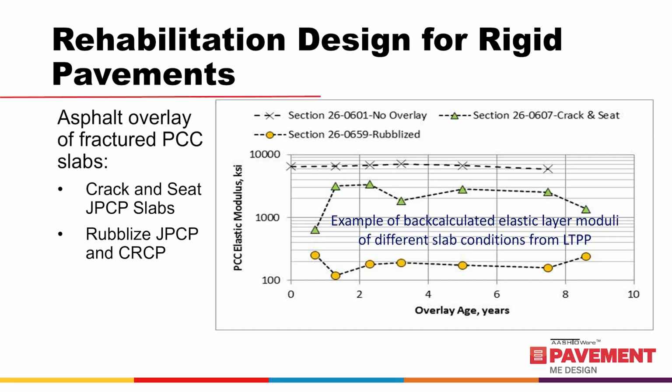Thus, the strength or modulus of rupture and modulus of elasticity must both represent the same time of testing for intact conditions. The PMED software cures the PCC layer after construction. So, the MEPDG suggests that 28 days strength and modulus values be used, or in accordance with how the PCC fatigue cracking relationship was calibrated.